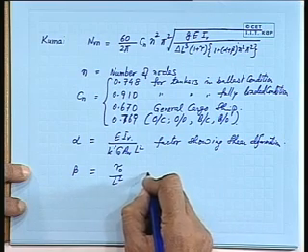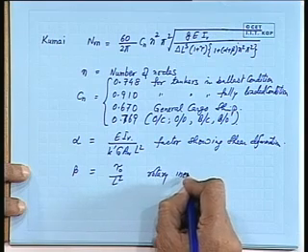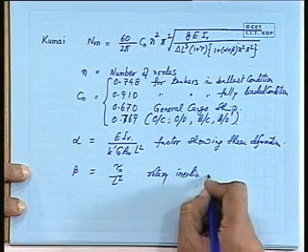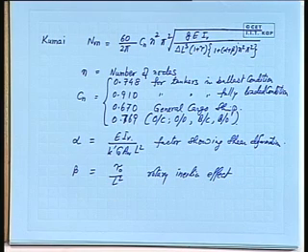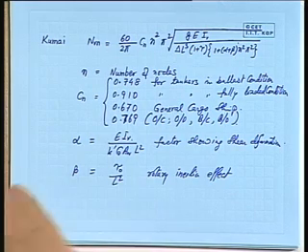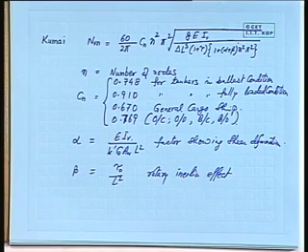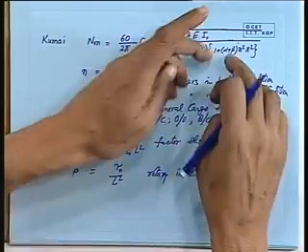This is the effect of rotary inertia. See, these two effects are there in the vibration of a beam. Okay. So when the beam is flexing, some part is going up and down, so you have to find out how that is changing the stress in the beam. That is known as the rotary inertia effect. So if you want to take it fully, then alpha and beta also have to be included here.